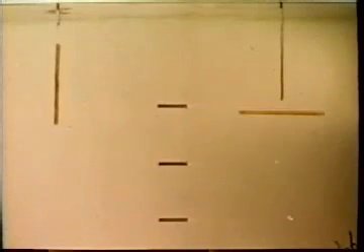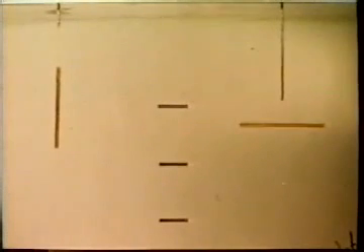At low Reynolds number, they have just half as much resistance to longitudinal motion as they have when moving perpendicular to their axes at the same speed. This is a property common to all long, thin bodies of revolution. When a rod falls obliquely, it drifts to one side.